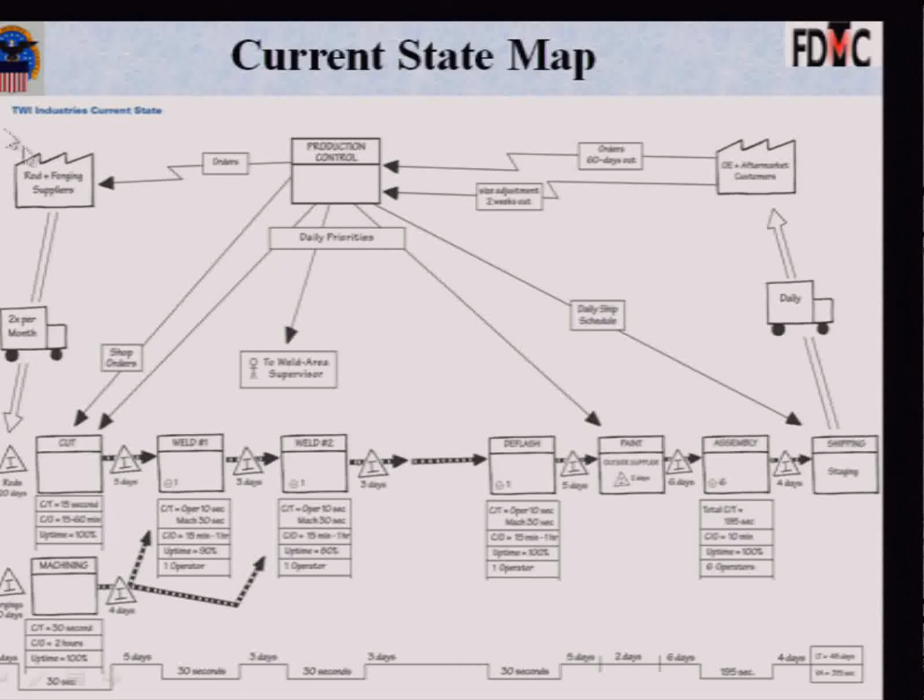I think that's unrealistic. On top of that, production control being done through MRP, I think it's suicide for any job shop, any high mix, low volume manufacturer to subscribe to that scheduling logic. MRP is fundamentally wrong, and you would like to be using finite capacity scheduling. Again, it is not as simple as sending dispatch lists to a few work centers. These dispatch lists may be sent to numerous work centers.